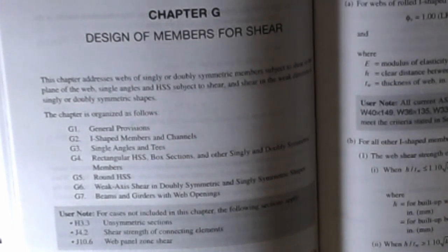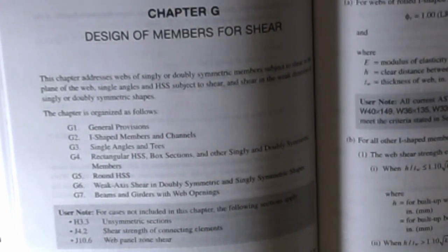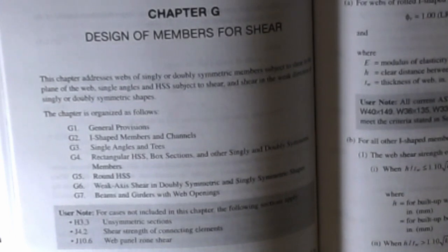However, if you get into very short spans with very high loads, sometimes these provisions will start to pop up. But 95% of the time, if not more, I find that when I'm designing a member for a structural application, the shear is not the controlling factor. Now we'll work through some examples just to show you what to do, but we'll take all of this with a grain of salt since we're not sure what scenario you're going to be facing in practice.